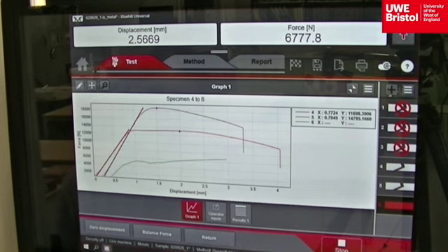This plot has a lower maximum load, a lower yield point. In terms of comparing ductility, it's displaying a lot more in the annealed medium steel form.